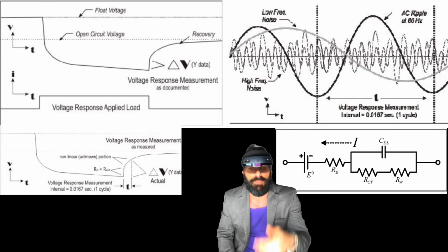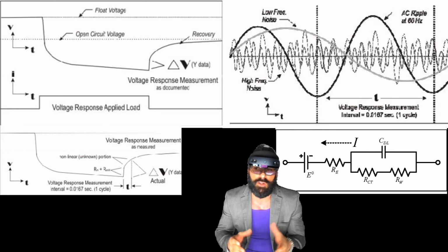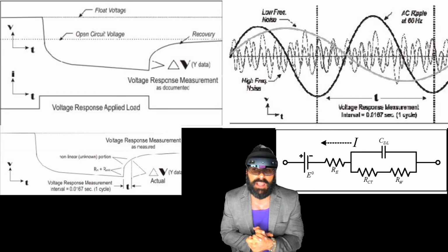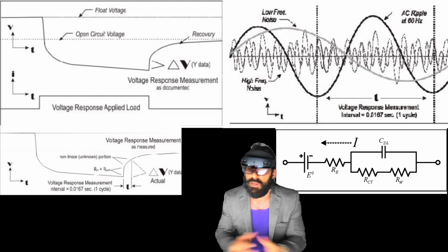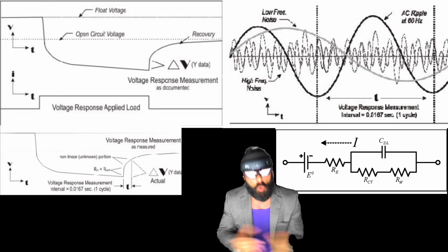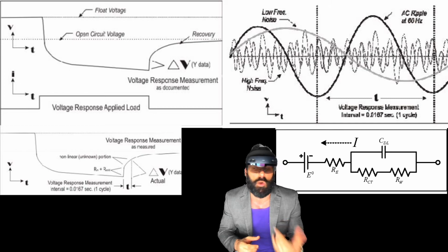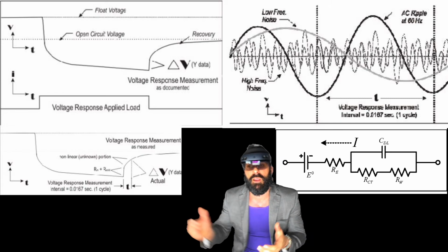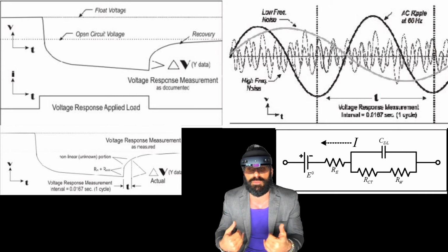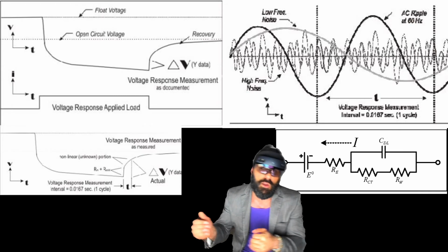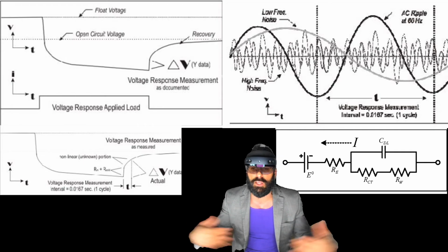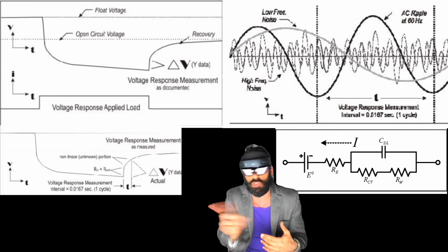On DC plants, I don't have an issue using AC-based meters because there isn't that much noise. But on big power systems, older power systems, maybe low quality power systems, and big UPS, 1 megawatt maybe, where they don't have a transformerless design, where noise is backfeeding from the switch mode power supply downstream in the load through the inverter. Again, everything goes into the battery system as a sink. There's a lot of noise there.